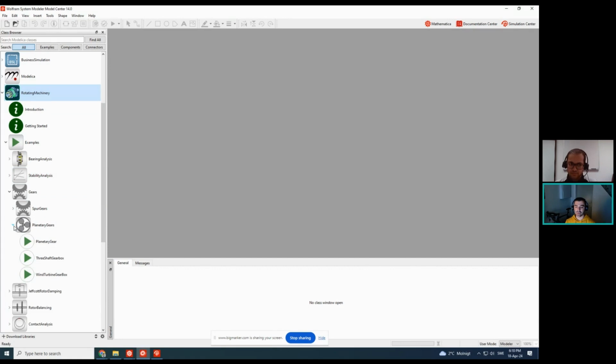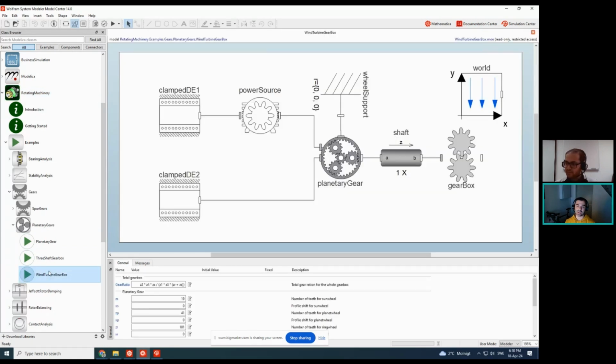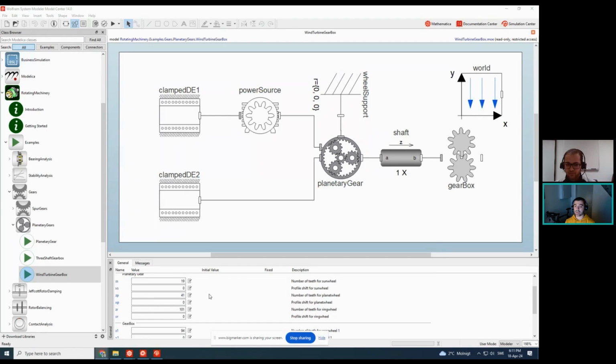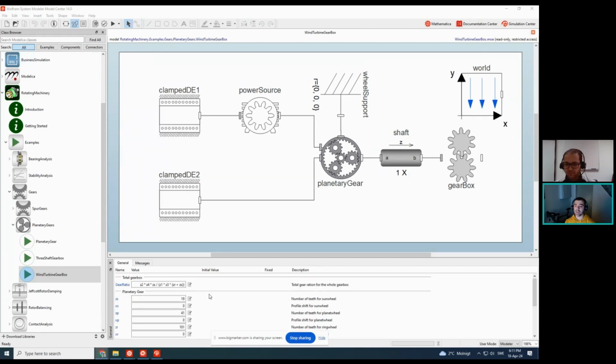You might have some certain constraints to test. We have so many components to design those systems, like bearings and gears. Other than that, we have contact dynamics. Also, we have almost 30 different use cases where you can just check. For instance, Ankit is looking for a wind turbine gearbox. Over there, you see the parameters. You can tune those parameters according to your own specific design and test how the dynamics look, how the stresses and the indentations look in a gearbox.